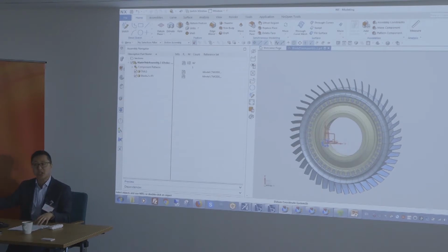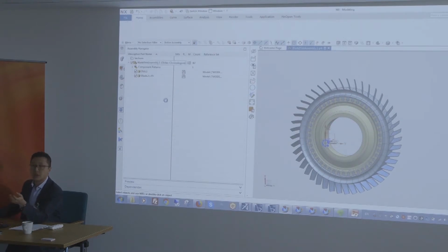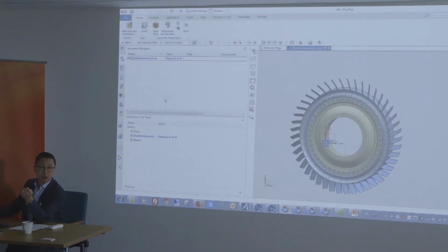But if an analyst makes changes for XY reasons, mostly for simplifying the heaviness of the model, you don't want those modifications to reflect on the designer's part, because it's not a real modification. It's just physical assumptions for structural analysis, for instance. So we have what we call the concept of idealized part, or idealization. Okay, so that's essentially a one-way highway between the designer and the analyst.